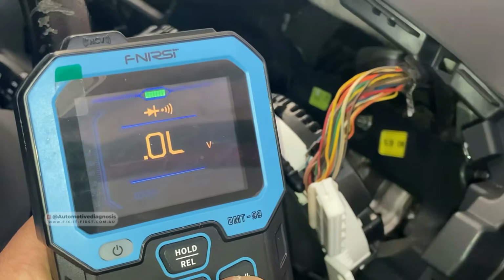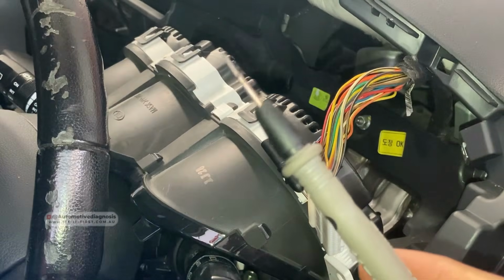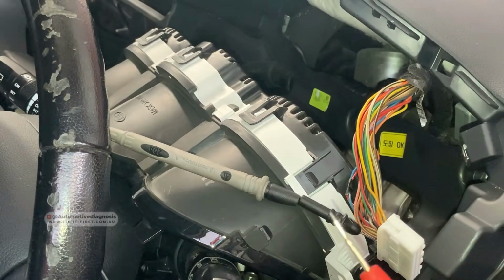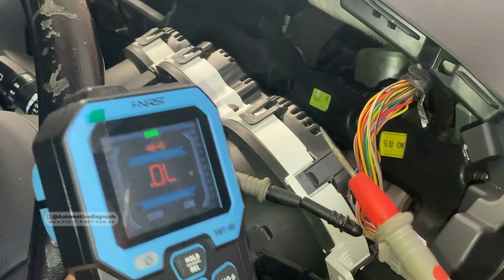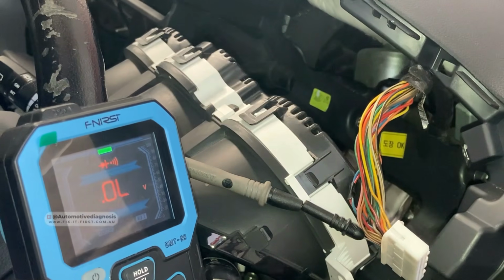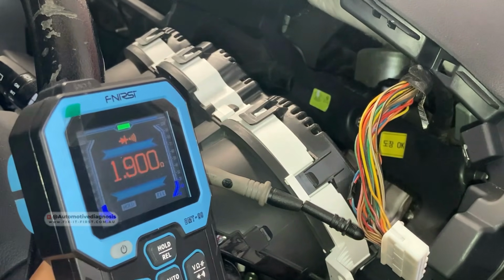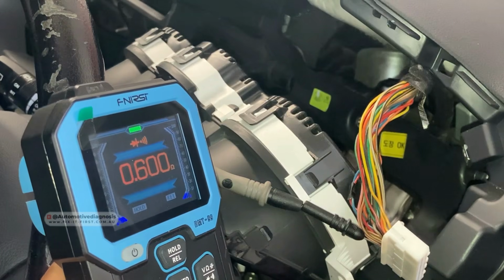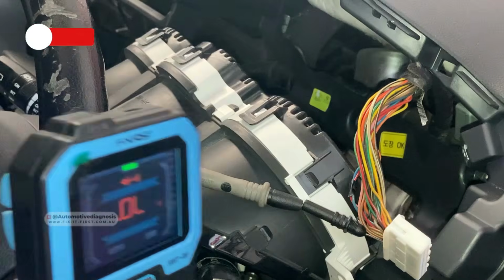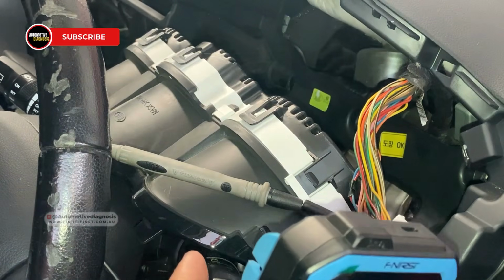On the multimeter, I select continuity. One end of the multimeter right here, and the other end is going to be on that test probe that I inserted on the joint connector, and see if there's any continuity. You see, there is continuity and the resistance value is 0 ohm. This shows that the wire is connected, there is no open circuit.